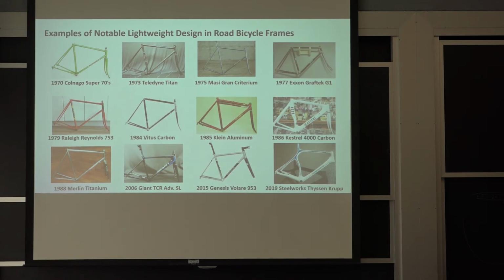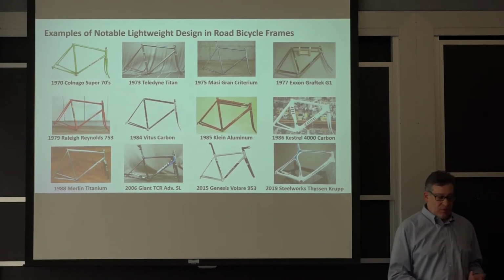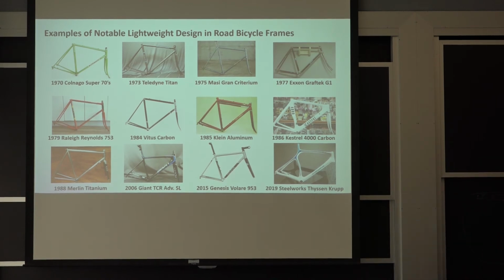And my point was exactly this: the geometry that's been developed isn't enough, the stiffness of steel and the strength is being wasted because the geometry is insufficient. And could there be a way we could maybe make tubes through hydroforming? I also put together, as part of the proposal, work with the Max Planck Institute outside of Dusseldorf, Germany, where they have a big steel research center, and we were going to develop a maraging stainless TRIP steel so that we could have higher deformation.